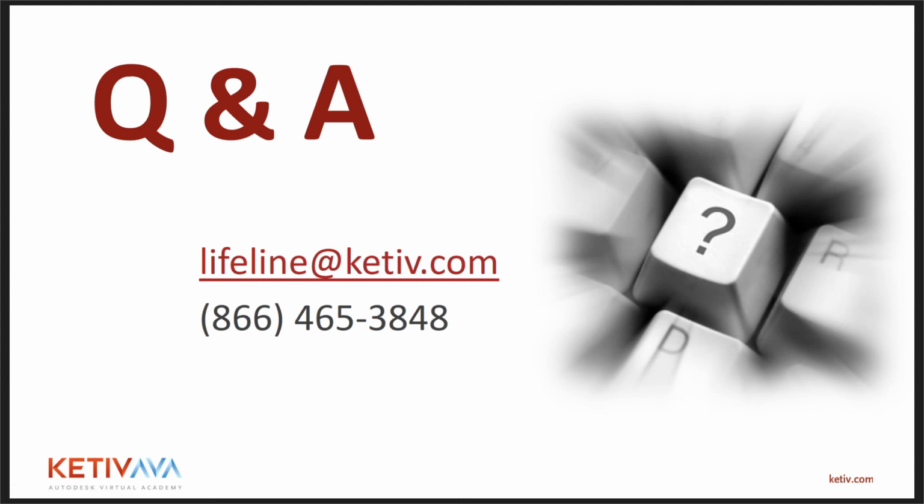Any restrictions against using English units? Not that I know of. I think you'd probably need to give us a little more information on what you might be referring to. But you can certainly mix units. You can create your own unit set and have millimeters, something metric, for a length unit, and a different unit for a force or your output. It's pretty easy. You can just change everything up. It's pretty configurable in that sense. Nastran's really aware in that case.